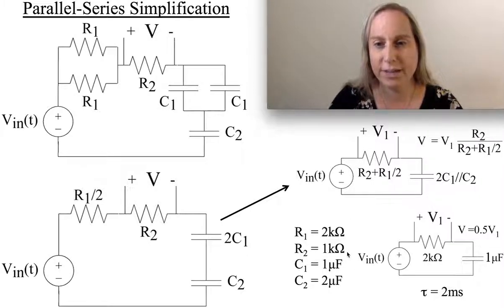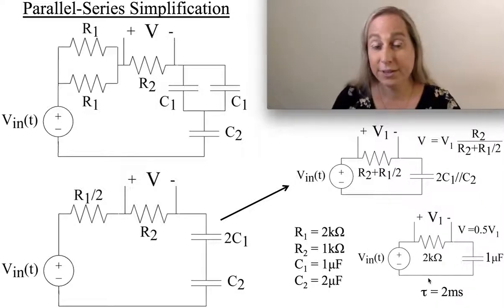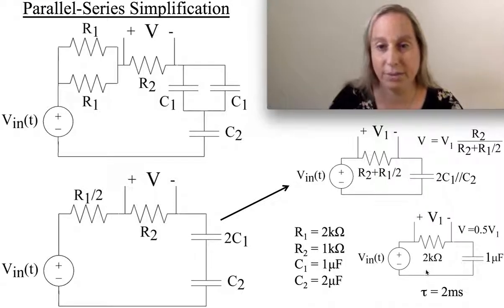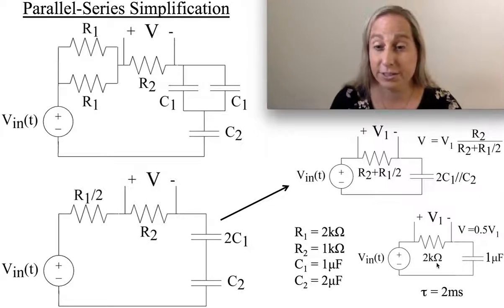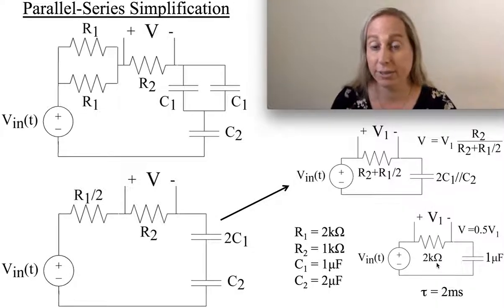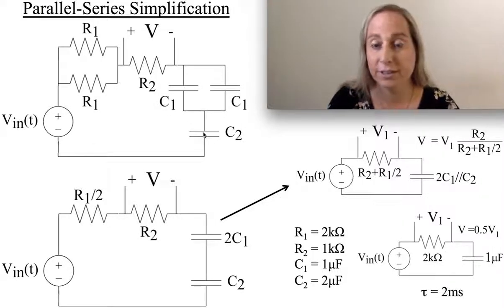So if I take these values, I can start plugging in. I look at the circuit, and all of a sudden, when I plug in the numbers, it's a very simple RC circuit with a very well-known time constant, and I can build from there. What we're going to find over and over again is that we can take these techniques and think about them either graphically or analytically to take what often looks like a very complex circuit and make it into a far simpler element to work with, and that we can often analyze just by looking at it, because we recognize the forms.